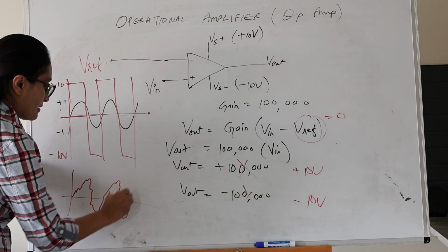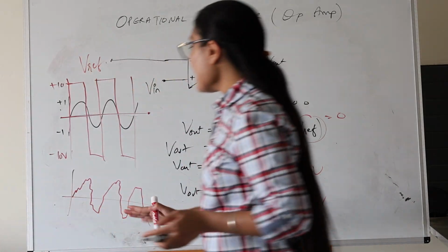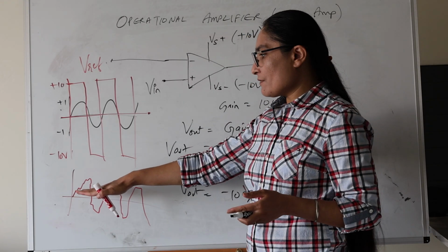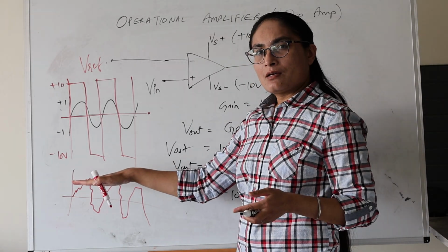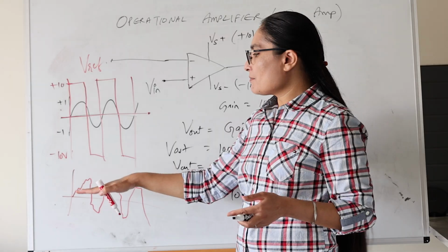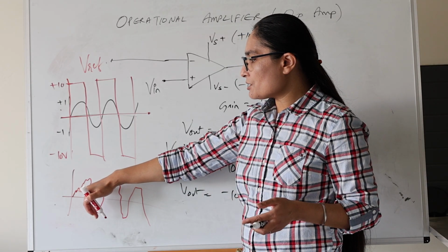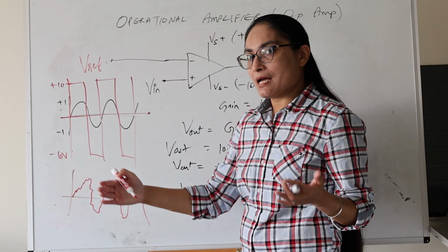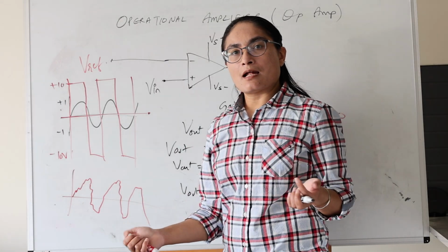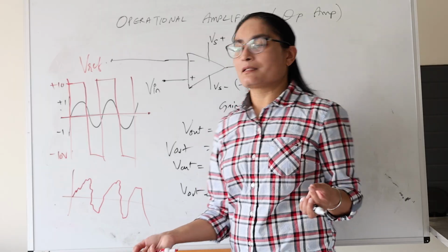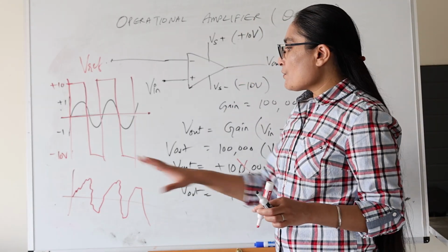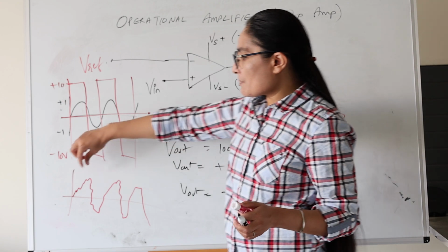So when that's the case, if you define a fixed reference, the sensitivity would be pretty high, because anytime it goes slightly above the jitter and slightly below the jitter, you will have a different output, and that's not practically true. So for those cases, we define some hysteresis.